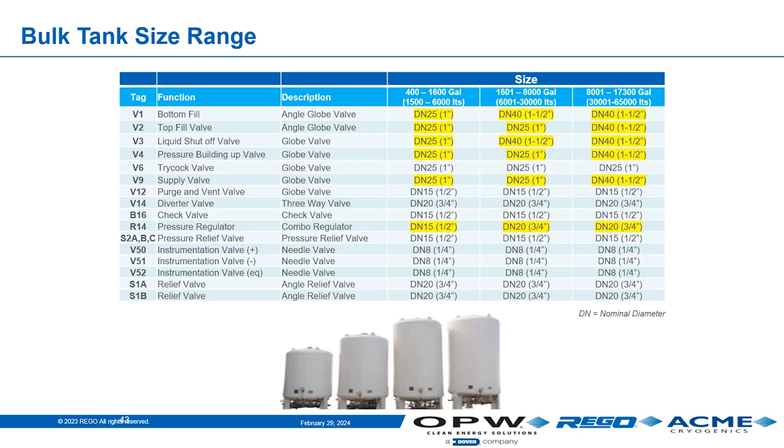So like I said before, on a bulk tank, 1,500 gallon up to 13,000 gallon are standardized. And the reason they're standardized is because of the shape of the heads. They get pre-made heads, and the same head is used, I think, for like a 1.5 and a 3 and maybe a 6. And then a different size head is used for the 9, 11, and 13. And all it is, the tank just takes a different shape, right? But the manufacturers are saving money by standardizing those heads.